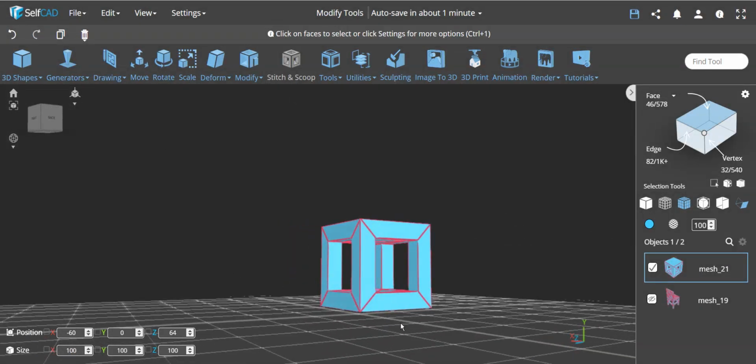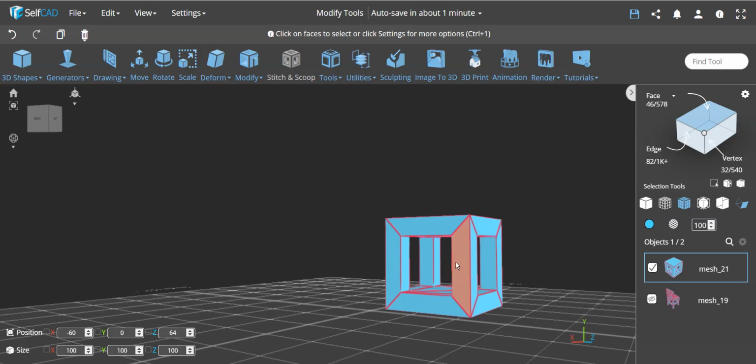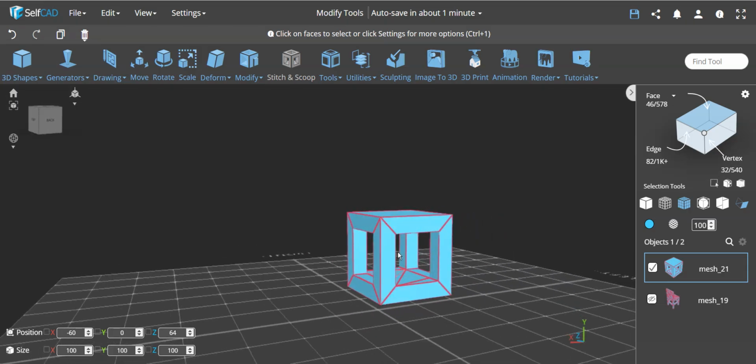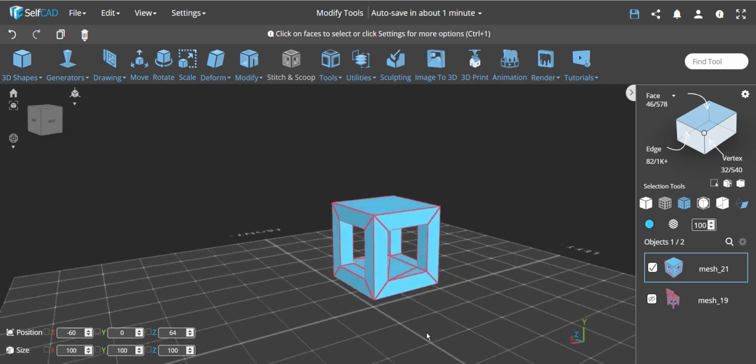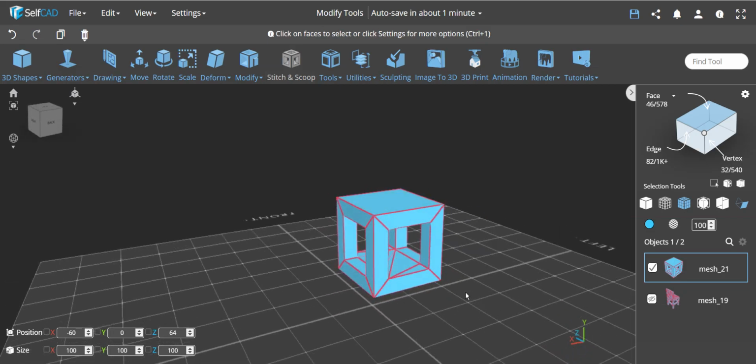So basically what I did is I divided it into 2 sections. This face cut only this one. Now I did over here, this one cuts this one. So the cutting from extrusion is limited to cutting simple things. If you need more advanced, there's always the Boolean tools, and the easiest way is to simply copy the faces and add thickness to it and use it in that way.